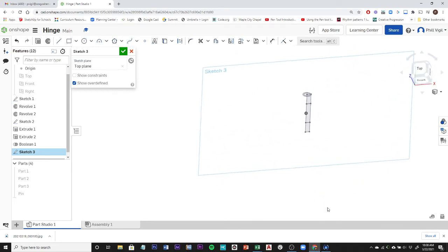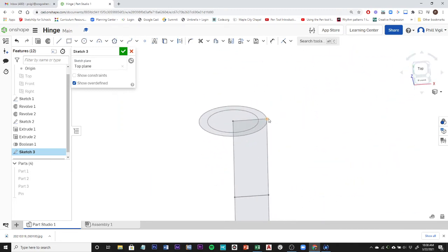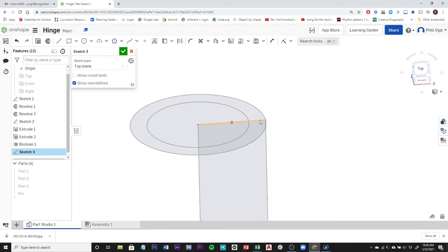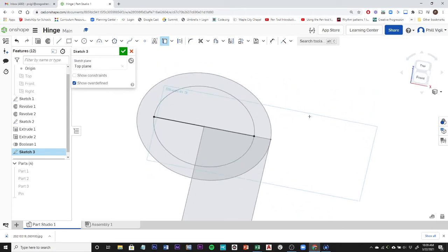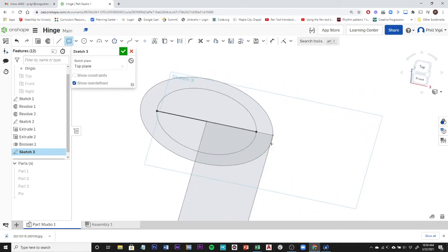So when I draw this plate, if the edge of the rectangle was attached here, it wouldn't be attached by very much material. So I'm actually going to start my rectangle somewhere in here so it's kind of inside the cylinder. So I'll go ahead and start my rectangle. I'm going to be modeling a plate. It could be anywhere inside here all the way to this edge. Let's say if I wanted to use that edge, just so we can practice using the Use tool. I'm going to use the Use tool and project where this circle intersects my current drawing plane. So right there. Now I can use that to start my rectangle.